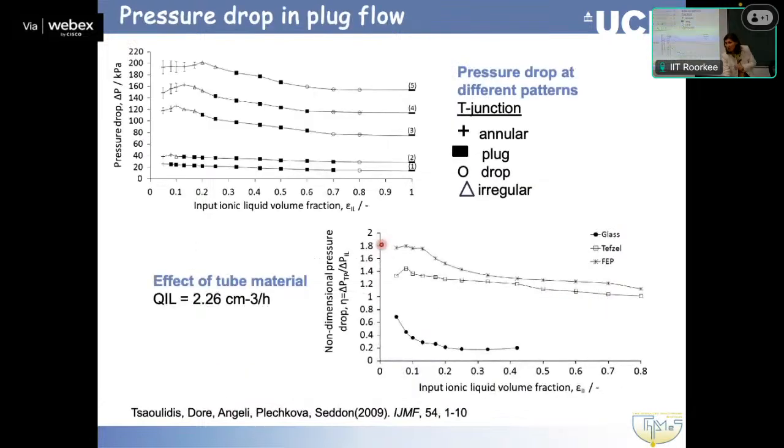One thing that is important, as we will talk later on, is scale up, because we need that to design our scale up manifolds. The other is to see what the energy consumption is, because at some point when we go to scale up, we will have this dilemma: do we increase the channel size or do we add more channels? One of the considerations could be the energy consideration. How much pumping power do I need to pump fluid in a certain channel size, compared to the overall gains on mass transfer?